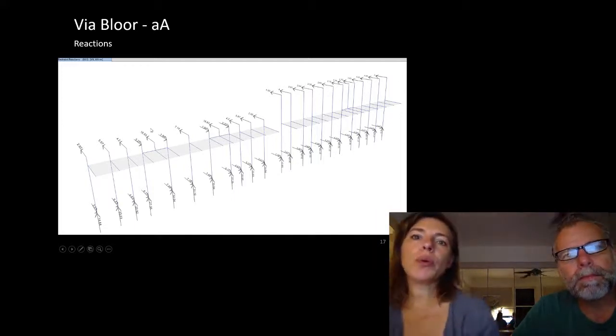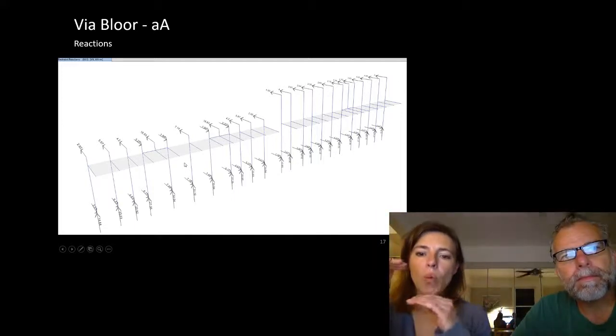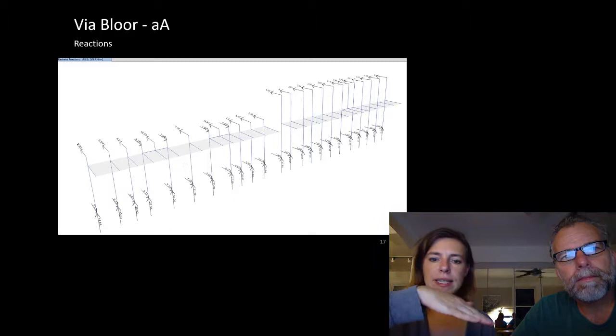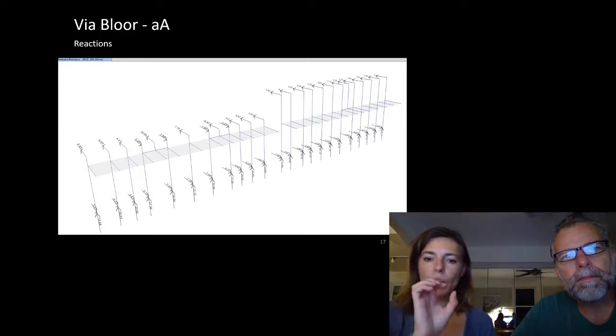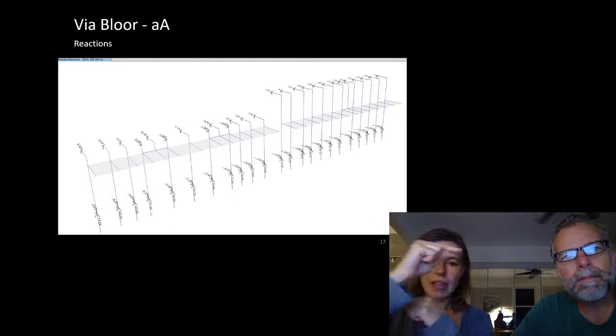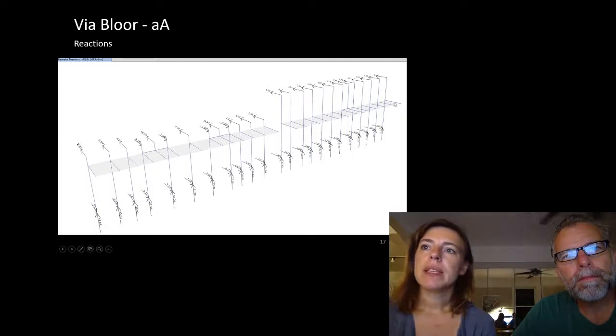What I want to show you guys is that as the canopy tries to dip down, it's causing a moment on the column, and we're resolving that as a couple. These canopies are identical. The only major variable is the length of the column they're connecting to.